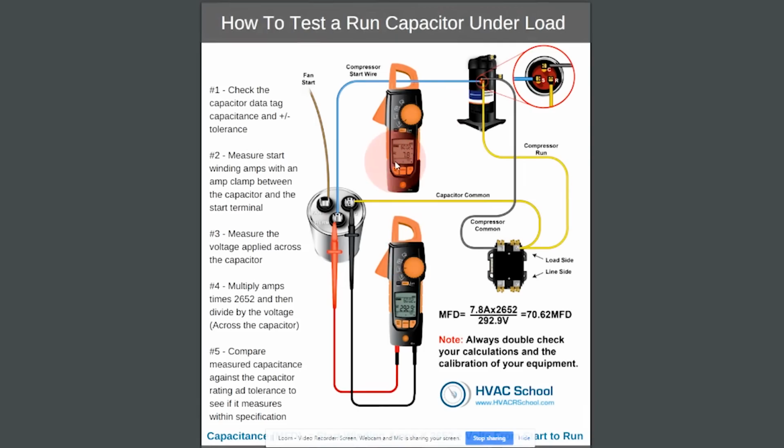The only way that you could have higher amperage on this start winding is if you had higher voltage or higher capacitance. And the voltage increases above the applied line voltage based on the back EMF that comes from the motor, which only happens when the motor starts to speed up. So that tells you that if anything, when you only have a run capacitor in the circuit, your amperage will be lower on your start winding when it starts than once it starts running, because that back EMF only comes up. This voltage only increases once this motor gets up to speed.